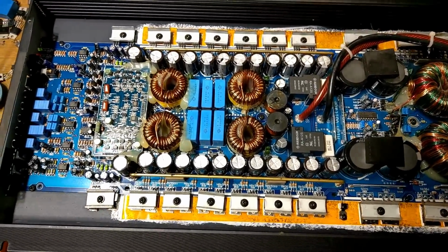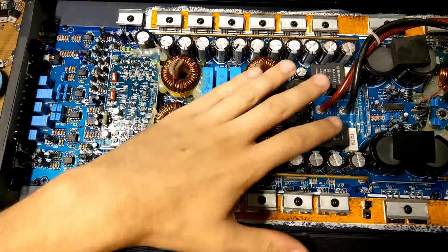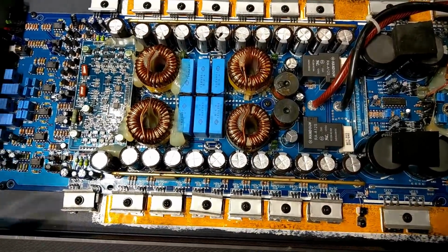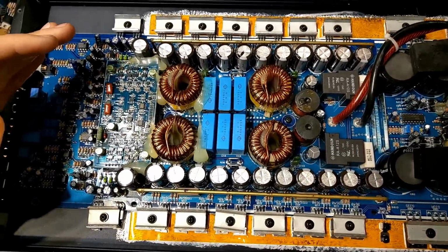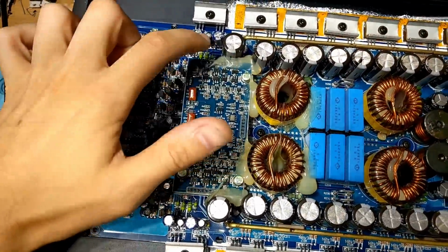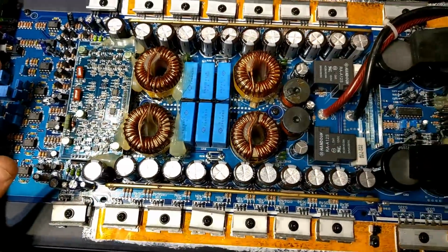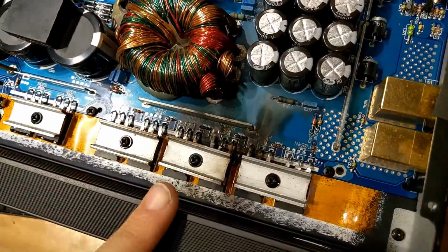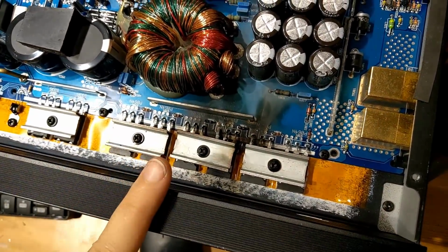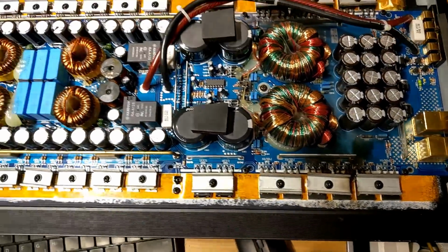I don't think this has probably ever been repaired before. This all looks clean, fresh as hell. There's no thermal paste smeared everywhere, as you tend to find in these ones that are repaired all the time. Yeah, the driver cards never come out of here, so this is fresh. Damn, this has lasted a long time. Unfortunately, as you can see, we've got some visible damage down here. The power supply section has blown, which probably means that the output section is dead as well.